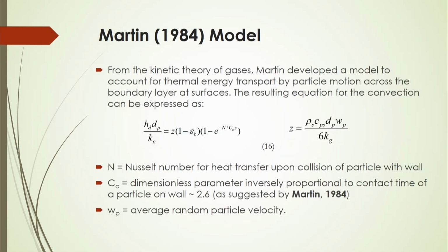Martin 1984 developed this equation to calculate the convective heat transfer coefficient in the dense bed medium based on the kinetic theory of gases, and developed the model to account for thermal energy transport by particle motion across the boundary layer at the surface. They developed this equation number 16 to calculate the heat transfer coefficient.